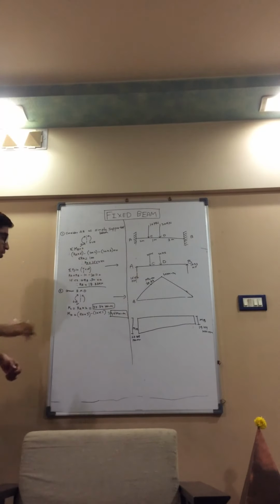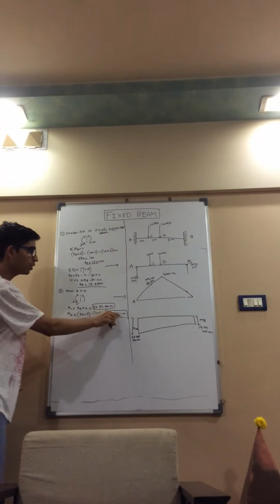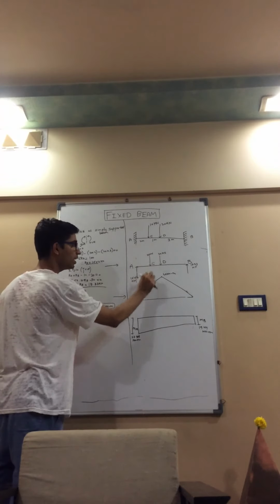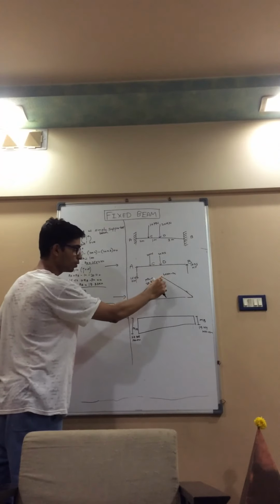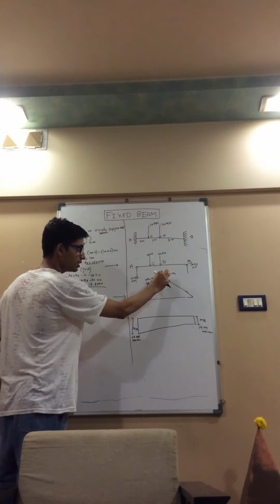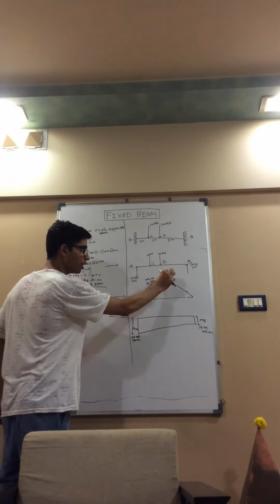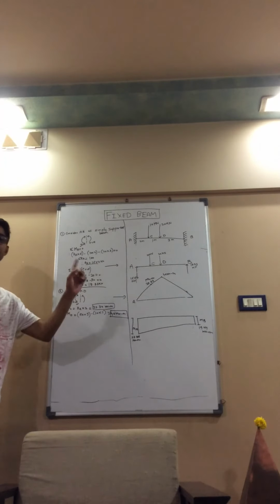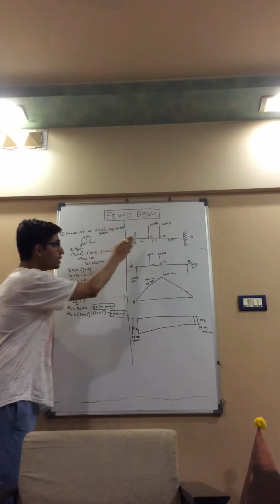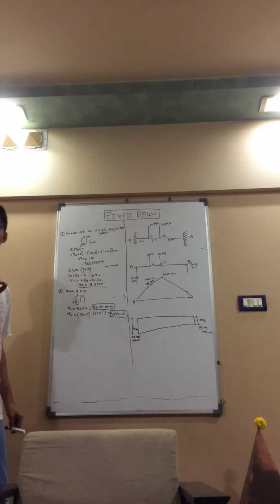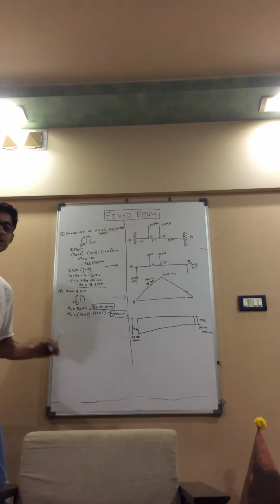After this, what is moment at point D? 40 kilonewton meter. So after plotting C, we are going to plot D, which is almost 7 kilonewton meter more moment. So here I plot a point at 40 kilonewton meter. This is point D. Again, students, between C to D, there is no load, no UDL, no force acting.